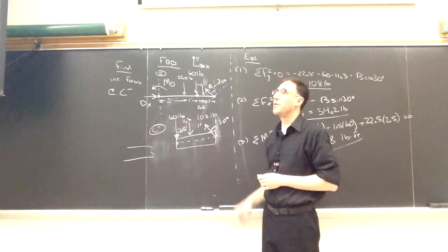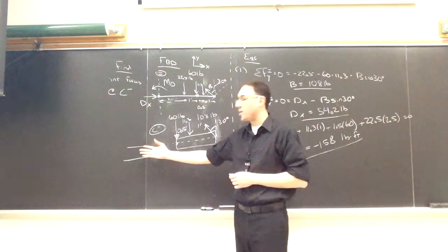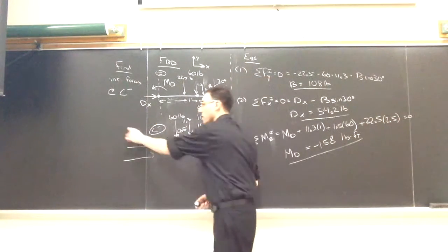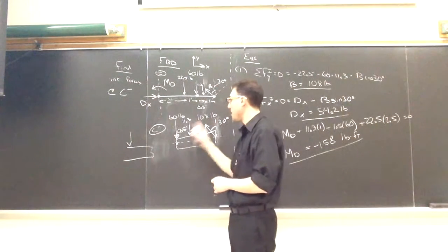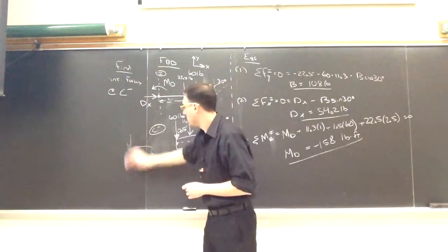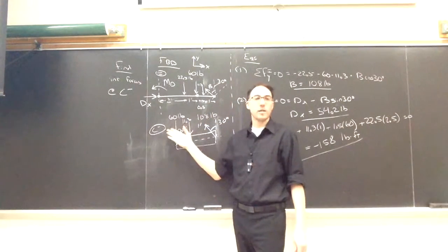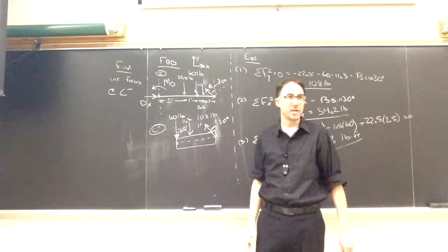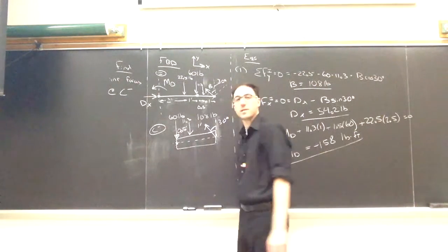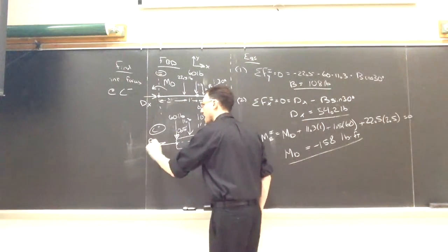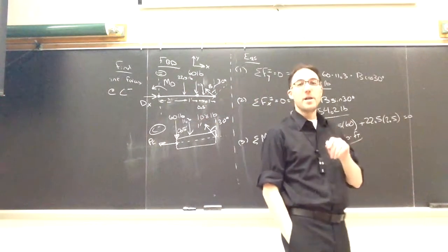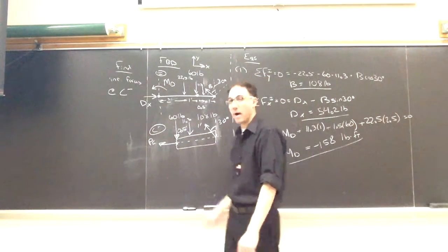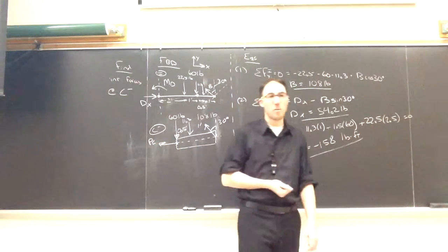This part of the beam doesn't know that the other half of that triangle is there. If I had chosen to take everything to the left of my cut, then I would have to simplify this part of the triangle that would be in that left side of the picture. But this side of the picture doesn't know it's there. All right, so I have the point load, the simplification of the distributed load that just touches CB. B is included. I'm assuming it's through the centroid. And then where I cut it, where I separated it just to the left of C, I can now see the internal normal force P. And note, in the homework, they've been calling the internal normal force N. They mean the same thing. P and N are equivalent. But I will always be using P to designate internal normal force.